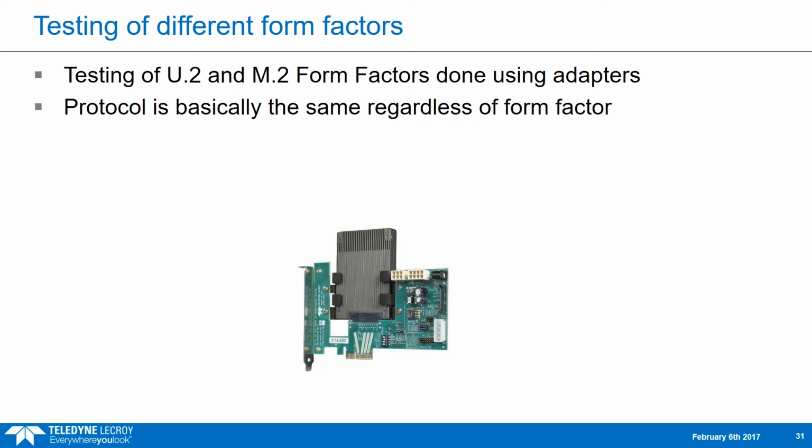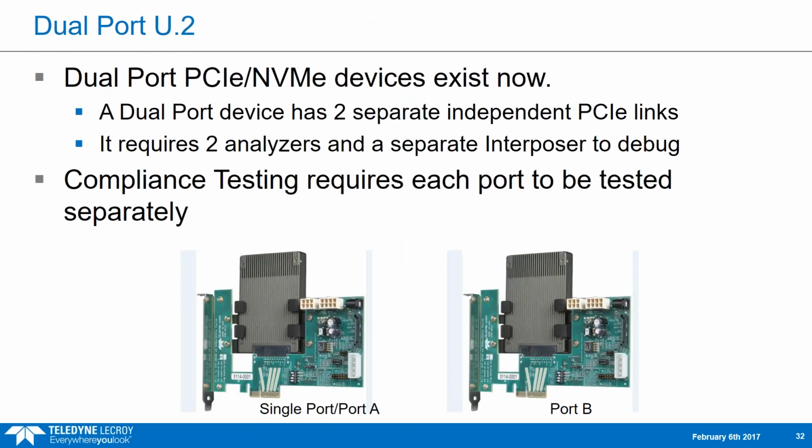You select the test cases, power on the DUT, then run the test cases, and a log file and a trace file will be created for each test case. So the process for running the tests is very similar to what it would be for PCI Express compliance testing or NVMe compliance or conformance testing.